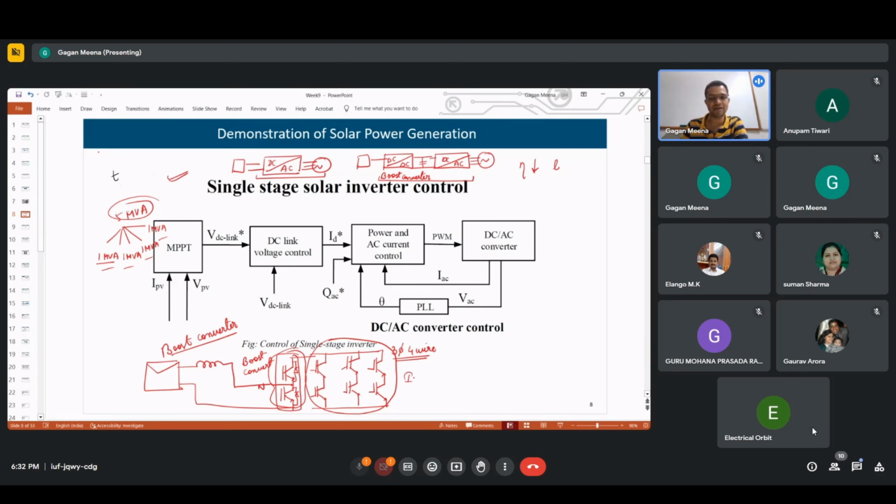That's why we have this capacitor in parallel with each leg. This is also called a snubber circuit. It will provide dV by dt protection against high rates of change of voltage. So these are the two important things here. Now we will see the